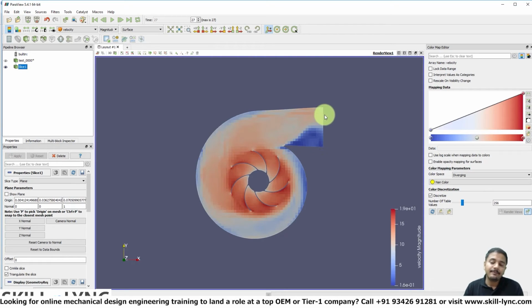Why is that? Well, we were basically saying that at the outlet our mass flow rate is fixed, correct? But in these types of scenarios, what's happening is you're encouraging reverse flow, which means technically flow can actually recirculate. In other words, flow from the outlet can come back in, which is called backflow. So what do we do in these types of situations?